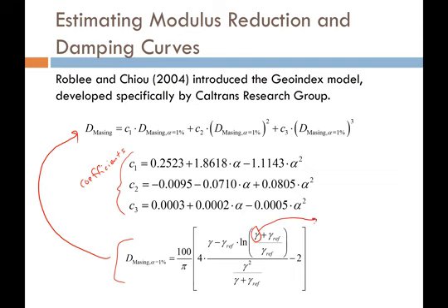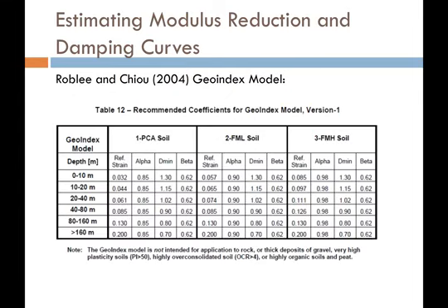So I'm glad I looked that up. This gamma here, you got to remember that it's gamma in percent. It's a percent strain, okay? This reference gamma is exactly as it comes in the table itself. So yeah, don't get confused on this. Remember that we're dealing with percent strain with just gamma, but gamma ref is just the decimal value straight out of the table.